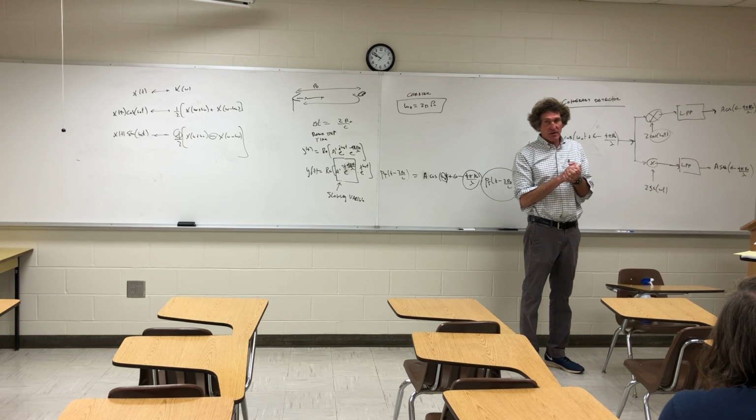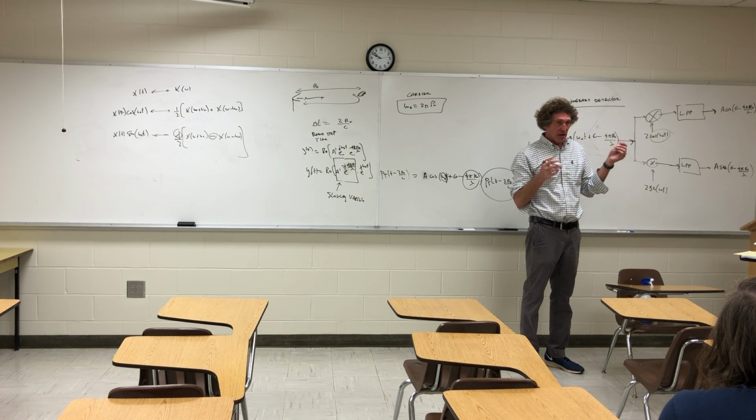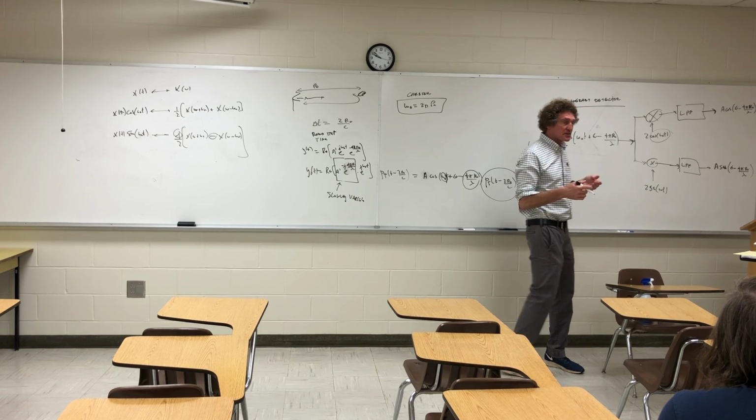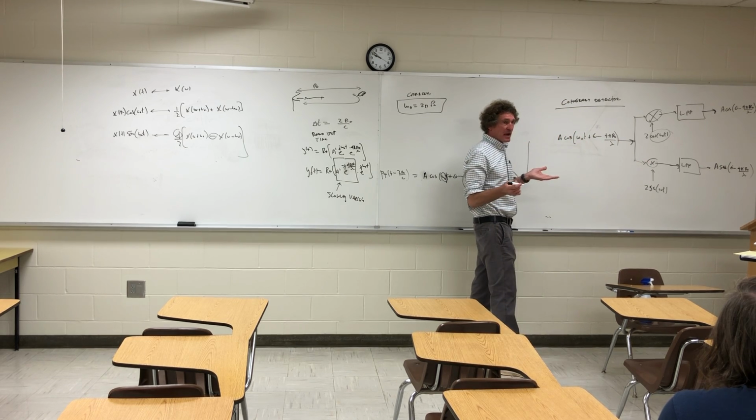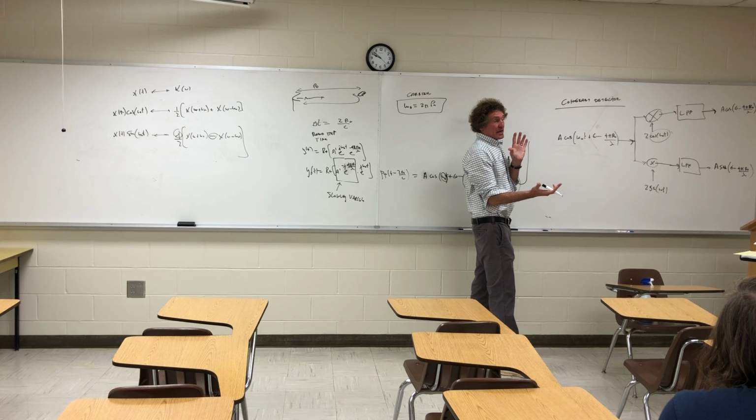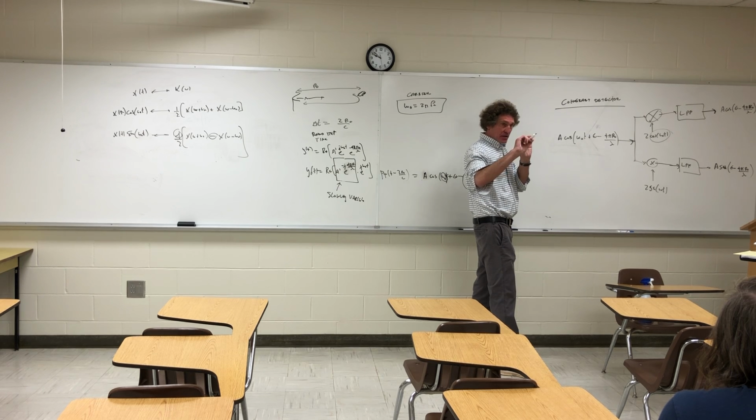They could amplify power. The magnetrons made radar real. Without them, I mean, we've got solid state devices that could do it now. And also a magnetron is something where you pulse it with electrons and it rings at a frequency, and the ring down of it feeds the actual antenna that senses things. But that ring down is precise, it doesn't change at all. Has anybody ever seen a magnetron? Do you know what I'm talking about when I say magnetron?